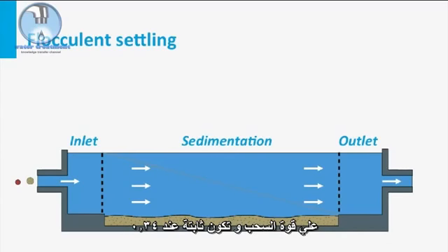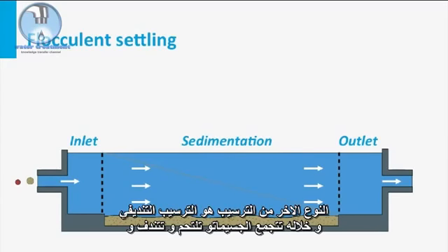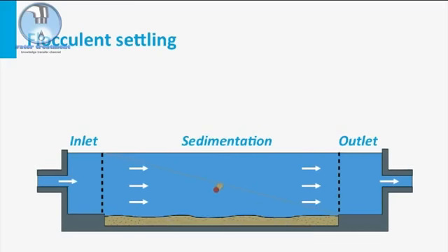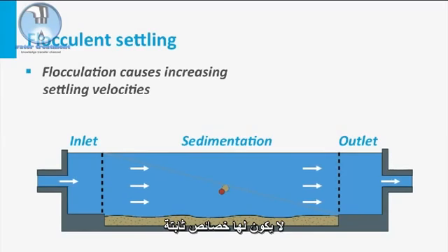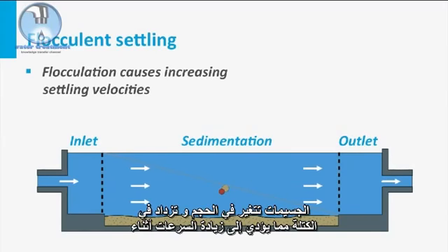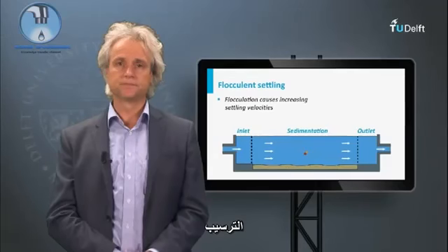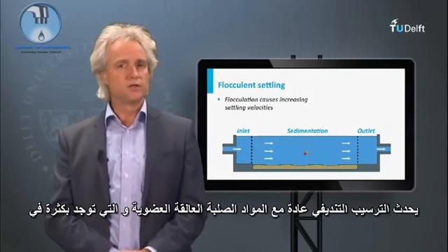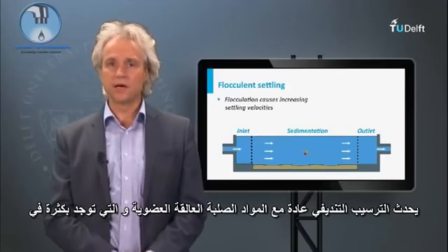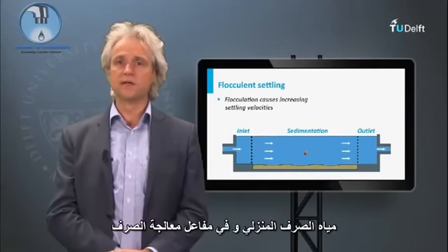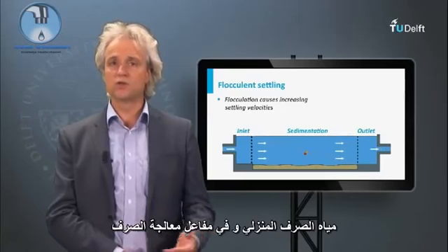The other type of settling is flocculant settling. During flocculant settling, particles agglomerate or coalesce or flocculate and have no constant characteristics. The particles vary in size and increase in mass, resulting in increased velocities during settling. Flocculant settling generally occurs with organic suspended solids, which are largely present in the domestic sewage and in our sewage treatment reactor.